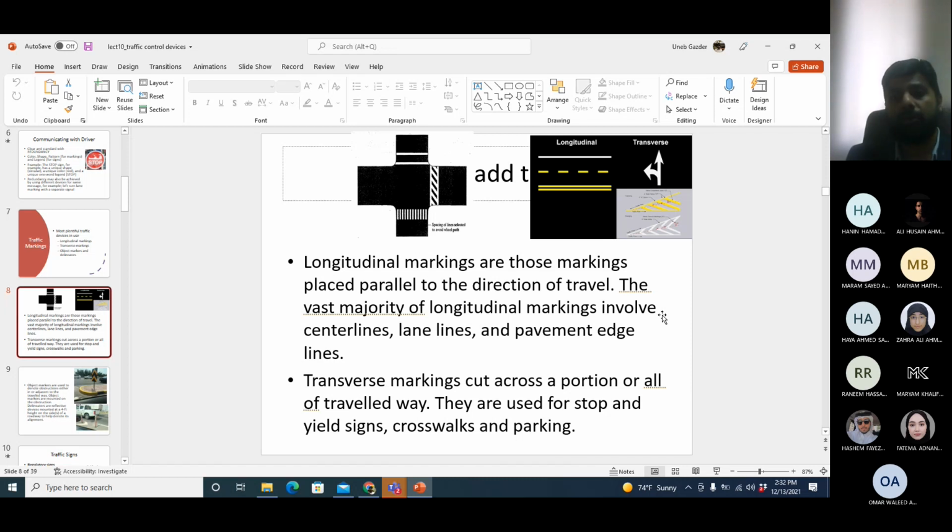Okay, so the stop line is solid, the yield line is dotted, for giving way. And arrow signs are transverse. And if you have parking places on the side of the road, the marking for these places will be transverse. Sometimes before the bridge or before the ramp, you see markings like them as well. They are also transverse because they are not completely along the length.